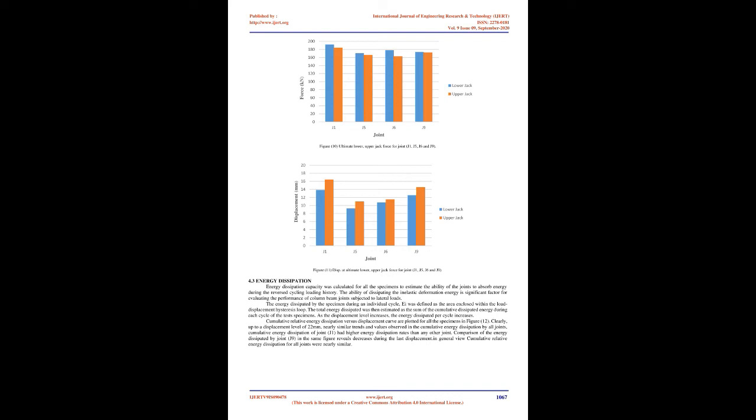These envelope diagrams show that in the squared rectangular column specimen, J1, with the increase in displacement in both positive and negative directions, the applied load was increased, and the load drop was not observed until an average of 13.86 mm. This is due to uniform stress distribution due to its squared shape.